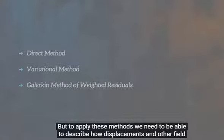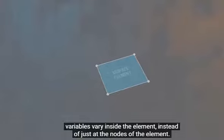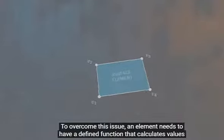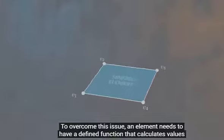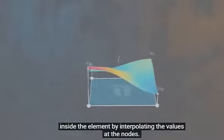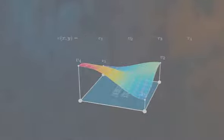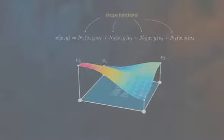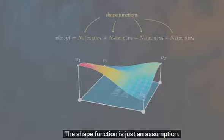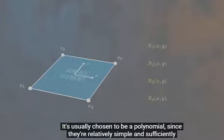But to apply these methods, we need to be able to describe how displacements and other field variables vary inside the element, instead of just at the nodes of the element. To overcome this issue, an element needs to have a defined function that calculates values inside the element by interpolating the values at the nodes. The shape function is just an assumption. It's usually chosen to be a polynomial, since they're relatively simple and sufficiently accurate.